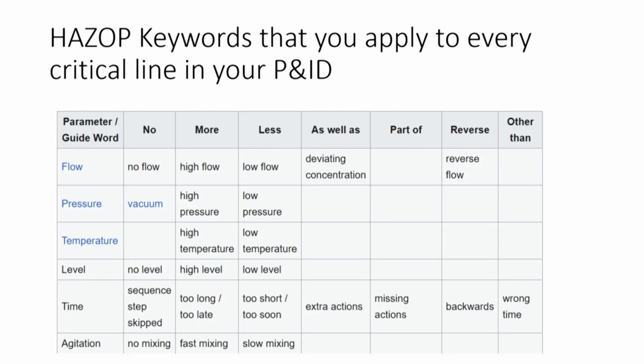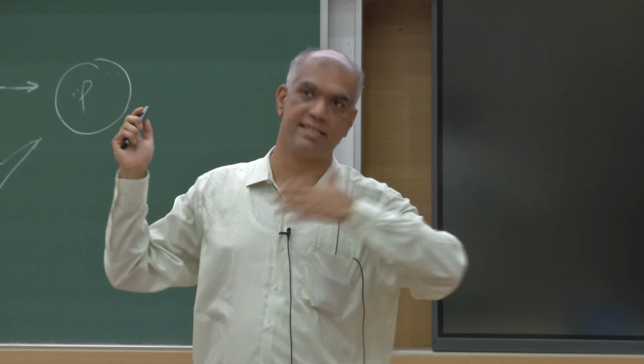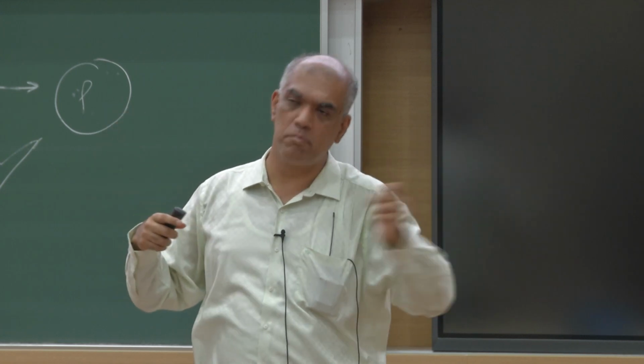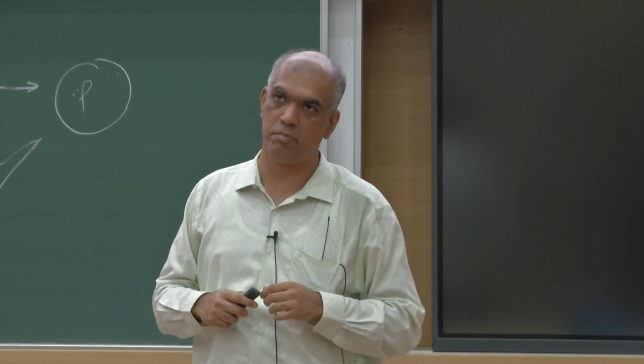HAZOPs. So typically the point behind a HAZOP is you first should have a P&ID ready, right? So choose an equipment or a couple of critical equipments, have the P&IDs ready. What is the role behind a HAZOP? Oftentimes plants have blown up or accidents, explosions happen because a certain piece of equipment fails. So suppose you have a reactor. And yesterday in CL678, we saw a video where there was some blockage in the cooling line, and it was a highly exothermic reaction, and the reaction blows up.